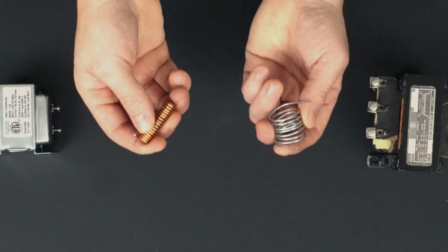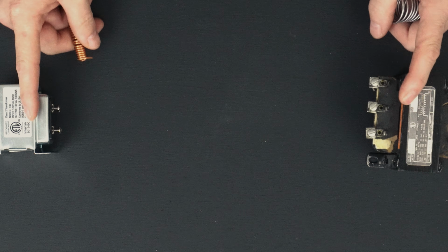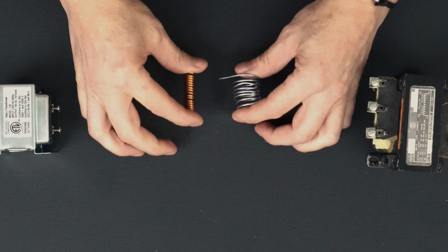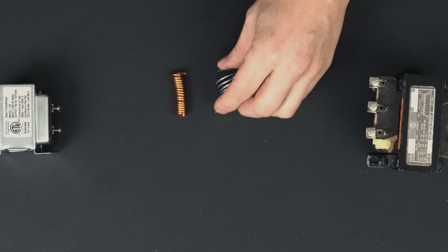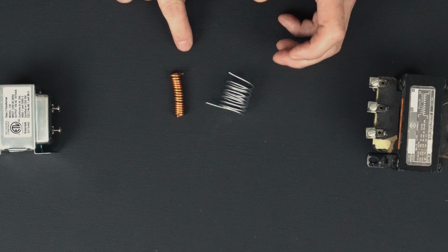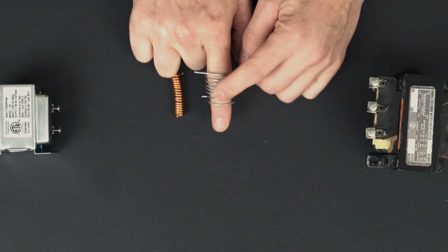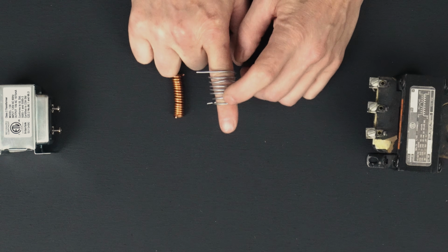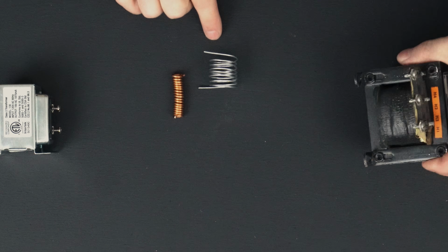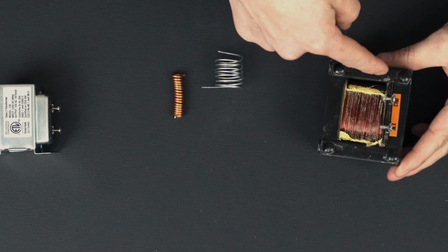Now, one thing that this does not have that these do is these have an iron core in the middle of them. So if you have 2 coils like this, you can make magnetism happen on the insides of these coils, but it's not very strong. So if you add an iron core to the inside of this, you can actually strengthen that magnetic field a lot. So these, if we turn them sideways, they actually have a bar on the outside, a bar in the middle, and a bar on the outside.